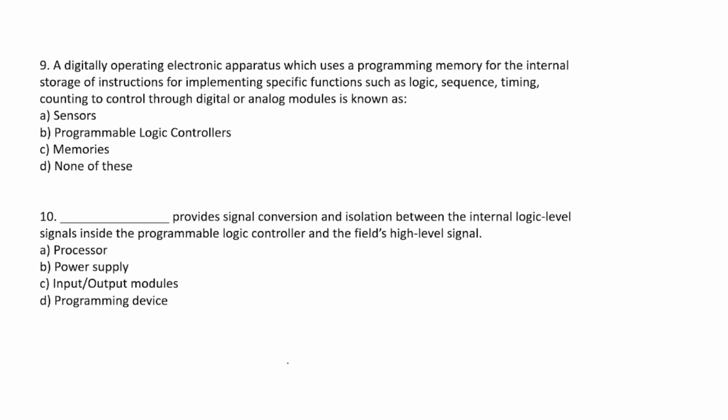The next part is the sensors in robotics: internal sensors and external sensors. Used in an industrial robot, internal sensors are basically there to control the position and velocity of the manipulated joints, and external sensors are there to coordinate the operation of the robot with other equipment in the work cell. There are also different kinds, such as tactile sensors, which are touch sensors and force sensors, and proximity sensors, which are used when an object is close to the sensor.